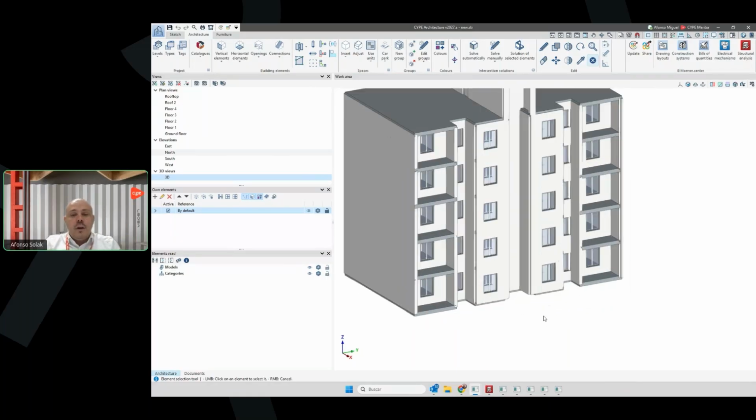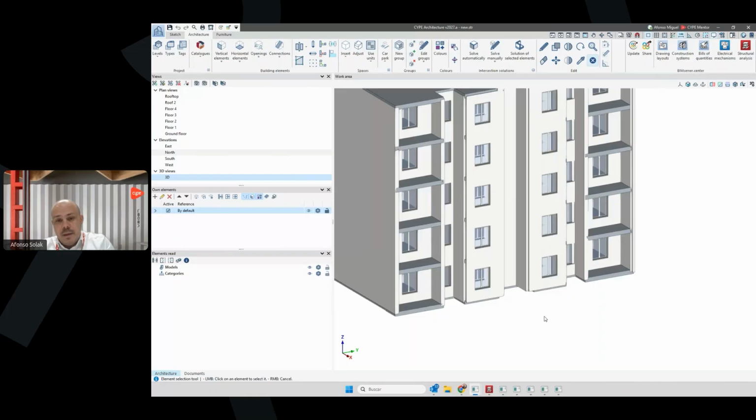Okay, of course, the quality of my DWGs, the number of layers, how good they are, will affect a lot the results in this process. Okay, so if you are working with a DWG that is very organized, and the layers group exactly the elements, you can get a good result. You can import it easily and use this system. Okay, if you have been working with this feature in CypeCAD for structures, maybe you already know how it works, and here is the same.